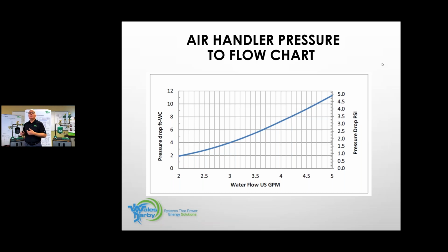Right? John just showed you when we were doing domestic hot water, figuring out the circulator, there's a pressure drop through that coil that has to be taken into account, plus the boiler. Okay? So besides the run going out to that air handler, we need to know what the pressure drop is across the coil. So I know the GPM, I know the length of the run, but I need to know the pressure drop through the coil. So in this scenario here, we're showing you a 4.7 water flow or GPM. The pressure drop brings you up to 4.5.